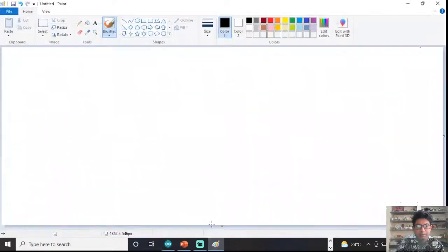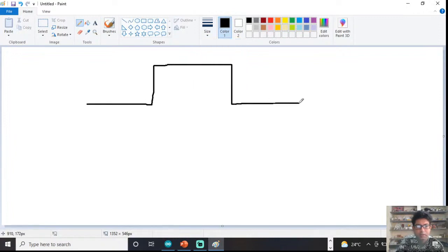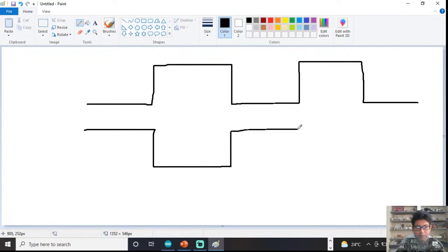practically, in a practical case, say this is my positive side pulse, and I give my negative side pulse, even though it is complemented. But the thing is, at once the high pulse is coming to the high leg, and at the same time the low pulse is coming to the bottom leg, the bottom switch. What will happen? Immediately the switch cannot turn off. It will take some time like this. So during this period the switch is still just switching off.